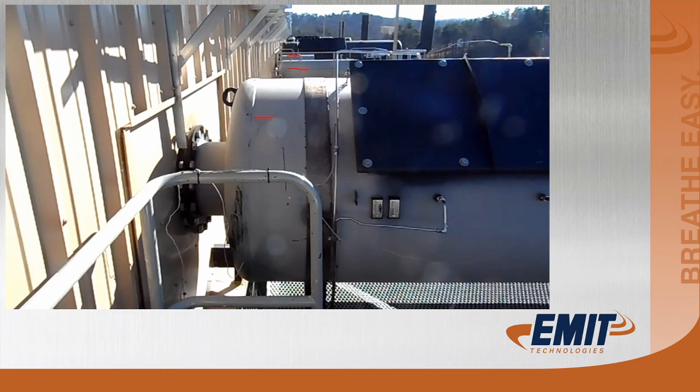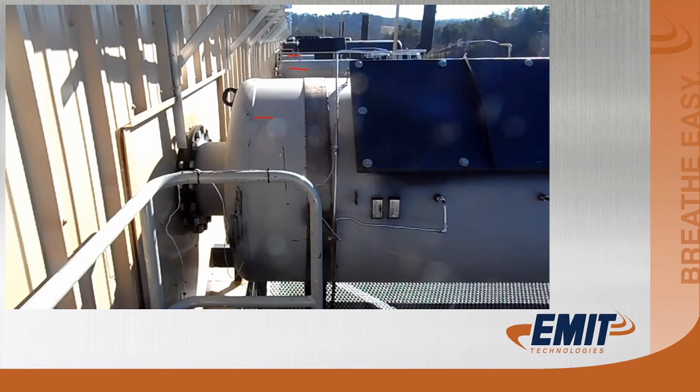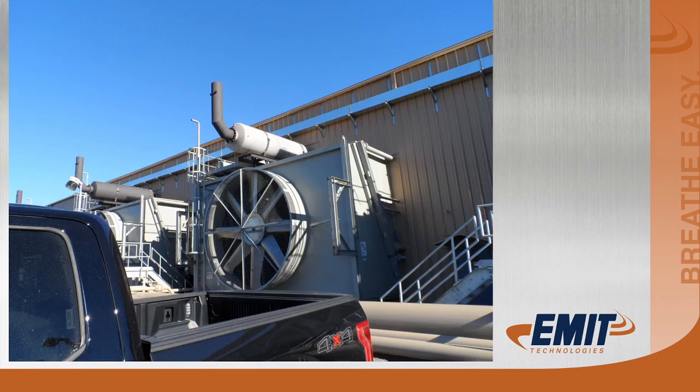These were all in the same location, and what was happening is they were having cylinder head failures on their units. And again, this is the same location that this element was on. This is the same housing that it came out of. And the temperatures were not showing high on their panel, so they were not shutting the units down. They had no record of overtemp, even though these housings had been turned white. In order for these housings to get that white, they literally have to be red hot.